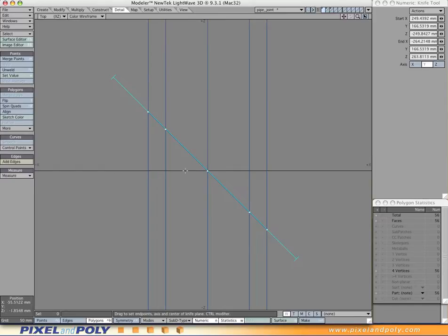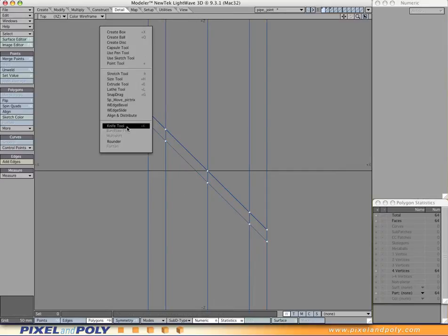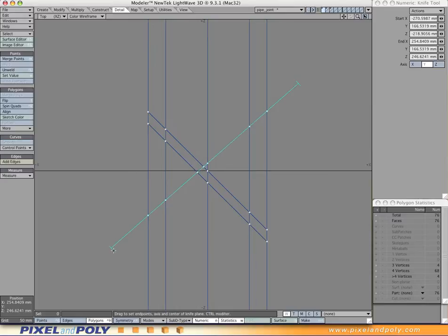So while I have this, I'm going to want to set up the beginning of our control loops on the outside of this T-joint. So before you click return to accept this, I'm going to click the right key and create my first control loop. And again, as far out as you go, that's how smooth that weld area will be. So I'm going to pick a distance about like this. It looks okay. I'm going to hit return. And then I'm going to do the same thing for the other angle.